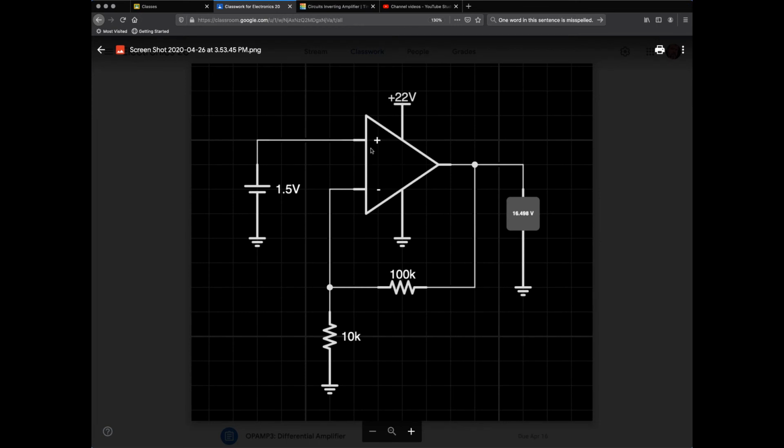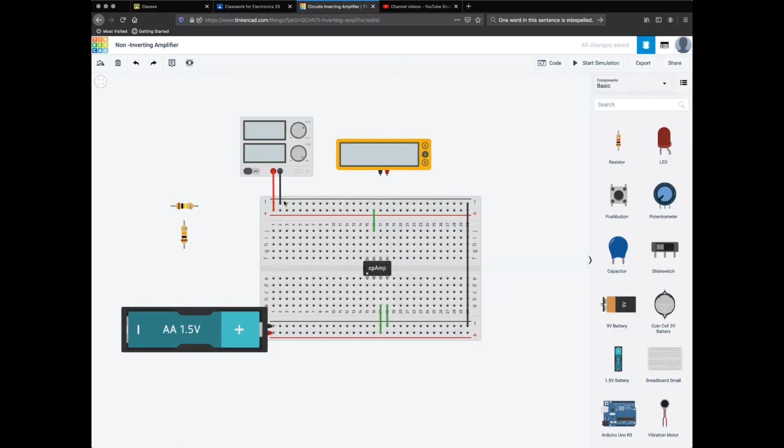So I've got my power going in there. I've got my op amp powered. What else do I need? Well, I have coming out of the negative, the inverting input on the op amp, I'm going through the 10K to ground. So the simplest way for me to do that is to take my 10K resistor, which is this one, and identify the negative input. It's that one. So then I'll take this and move it over here and release it.